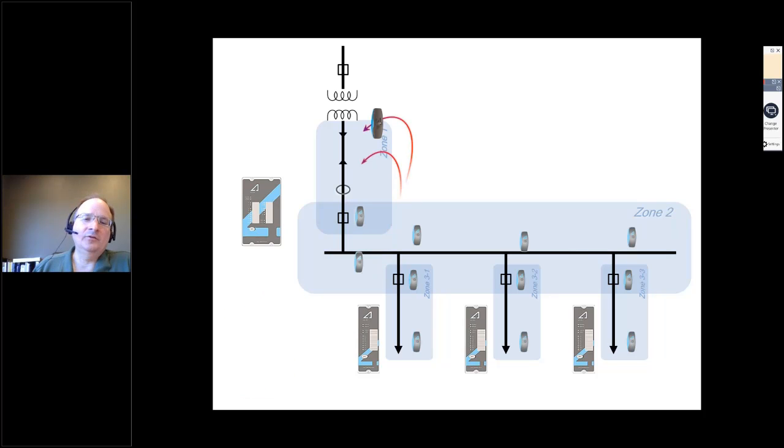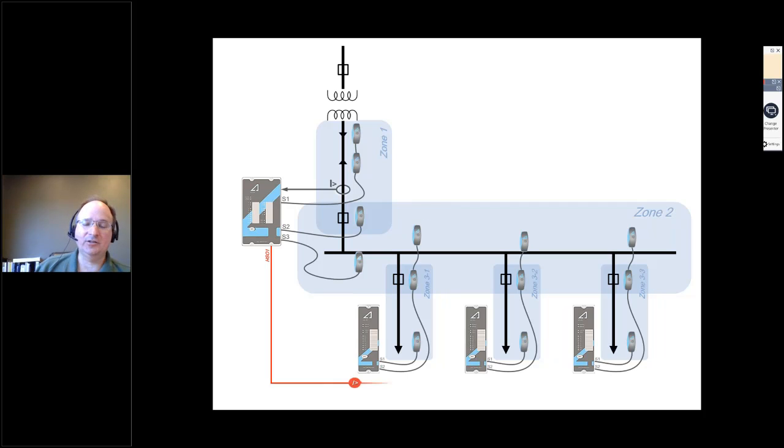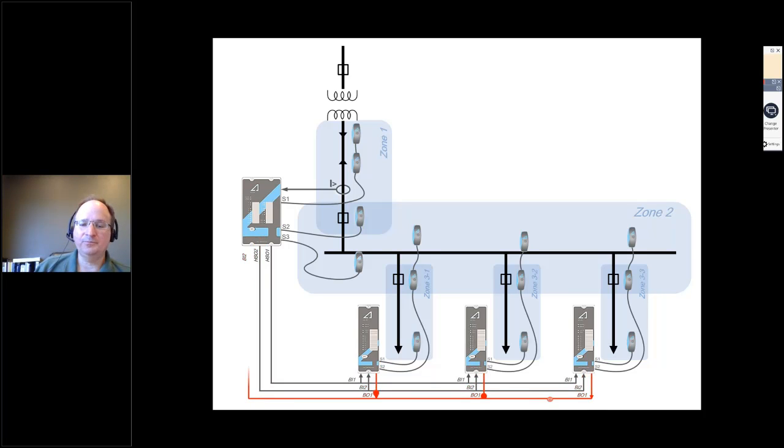This is what we would do in either new equipment, right at the factory, or in a retrofit application in the field. We would connect the current transformers to the protective relay. Wire in the light sensors. We can wire directly to the protective relay or to the protective relay gateways you see below. We call those AQ101s. And then we connect our high-speed outputs to the binary inputs. Now we connect our trip signals to the circuit breaker and/or the arc quencher on the secondary.